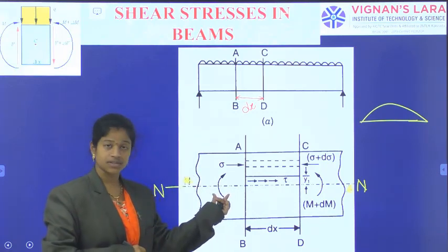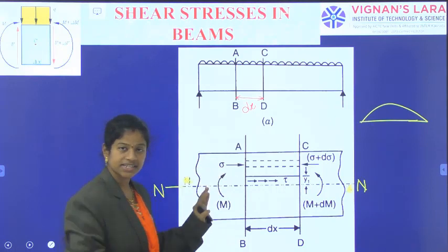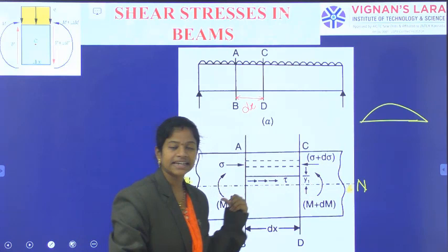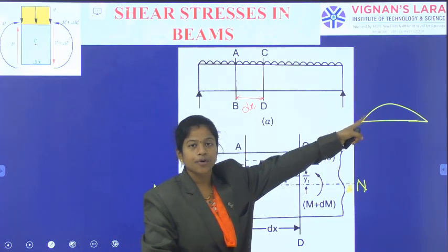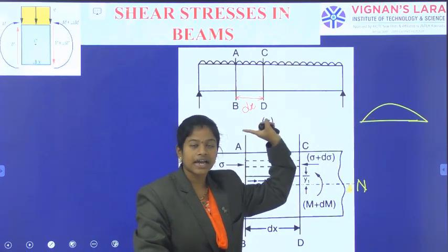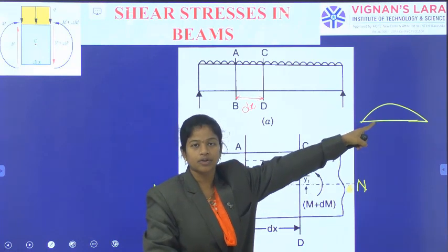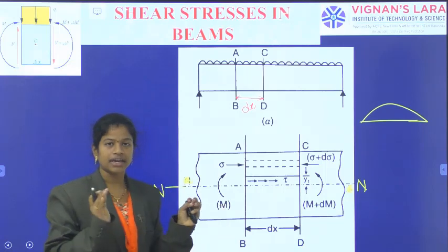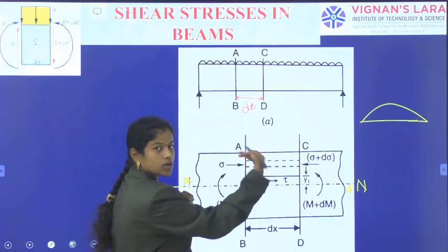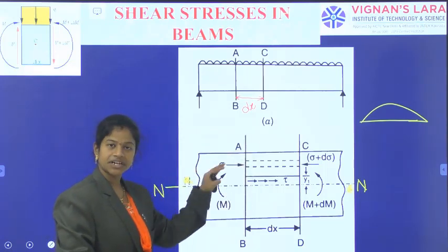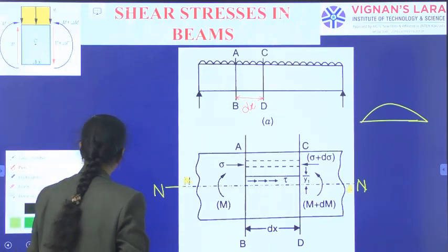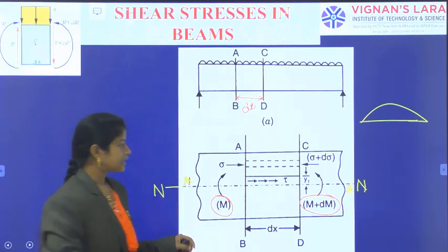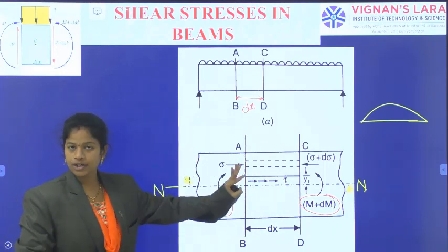That's why these two curves, it is causing sagging on this section and it is causing sagging on this section. So both are indicated like this because a simply supported beam with UDL over entire length will have a complete positive bending moment over the entire length. That's why these two arrows were like that. Okay, this one on the right side is causing sagging moment. This one on the left side is also causing the sagging type moment. Right? And just up to that you should have to observe.